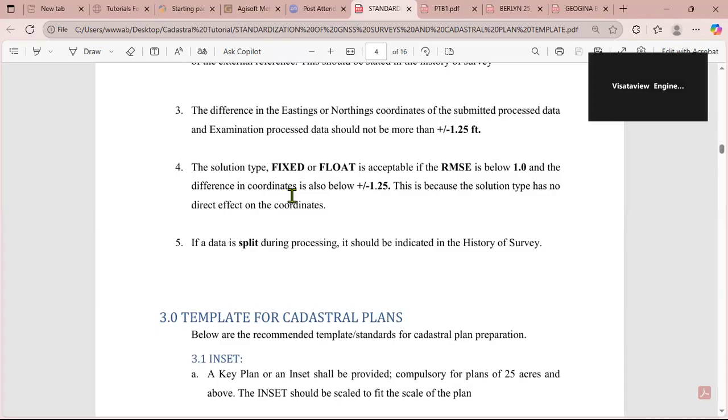Or, if it is a TBM you are talking about, you can set it on the field or the land you are working on. You set one base there, and then use one rover to pick your data, and the one that you have set there will become your TBM. Please, do you get it?